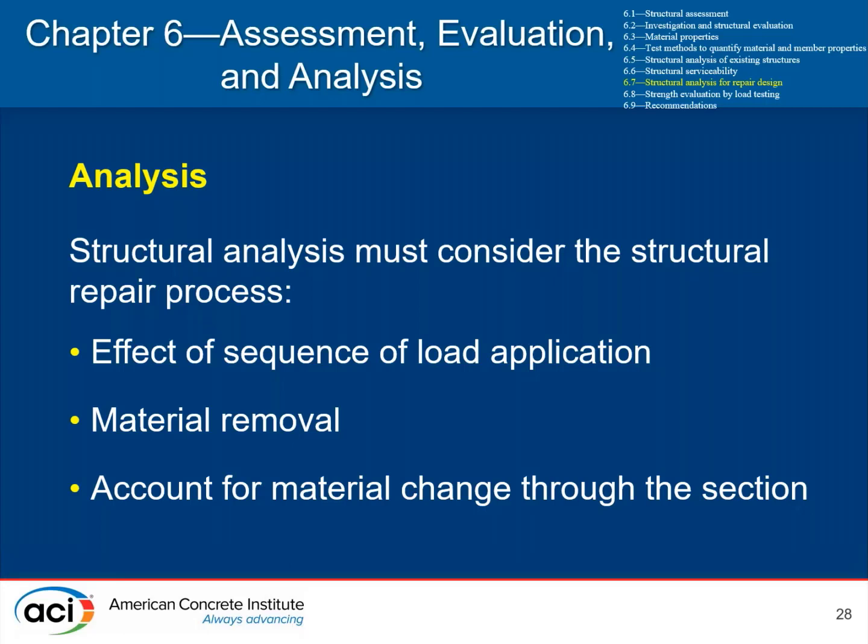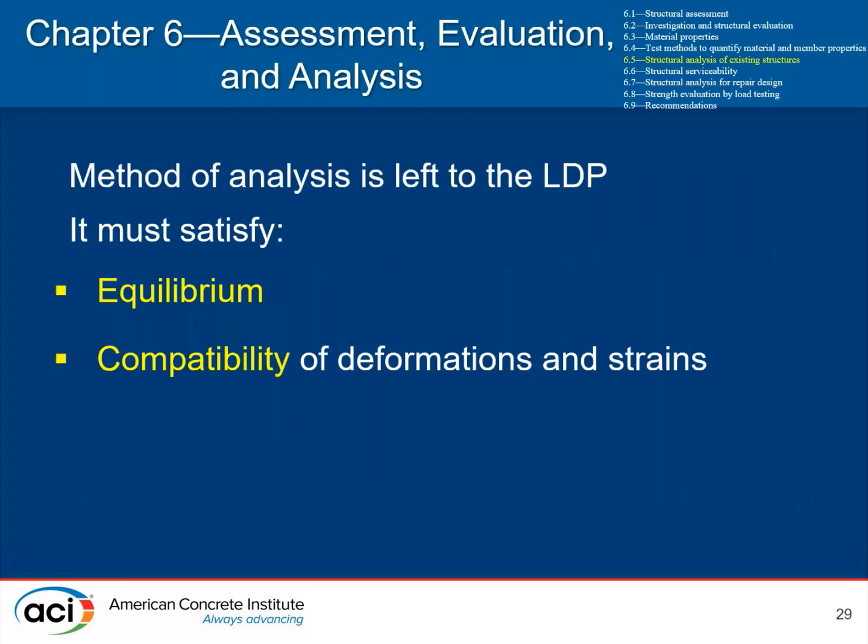Additionally, there are material changes through the section when a repair is conducted. You have situations where previous repairs might have different properties than the original construction, or the techniques and technologies that are being used to repair the structure can additionally create differences throughout the section that need to be accounted for.